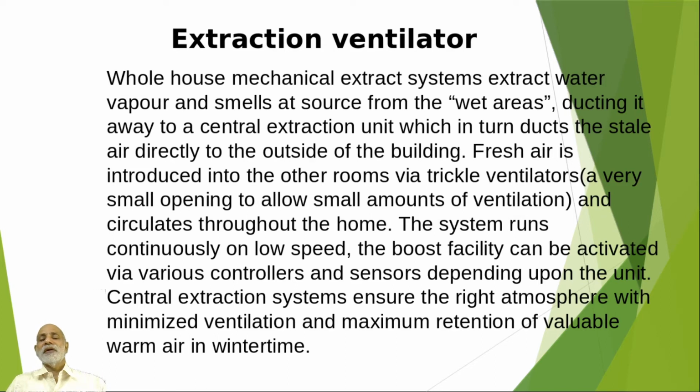From there, the collected polluted gases or polluted air are taken directly to the outside of the building. Simultaneously, fresh air can be introduced via trickle ventilators. This extraction ventilator runs continuously on low speed.